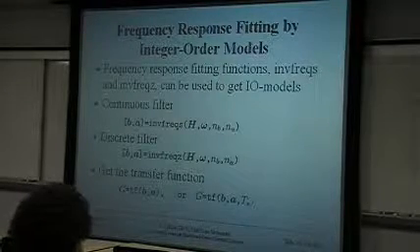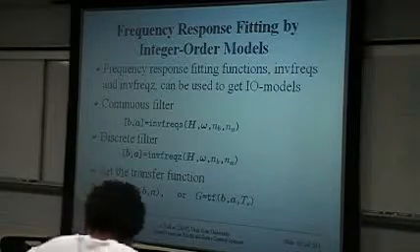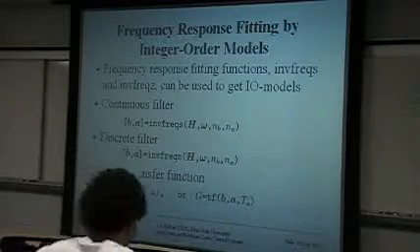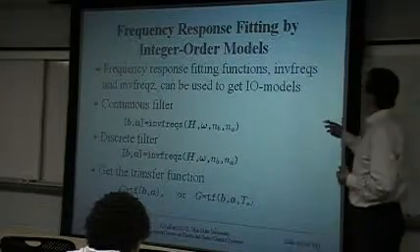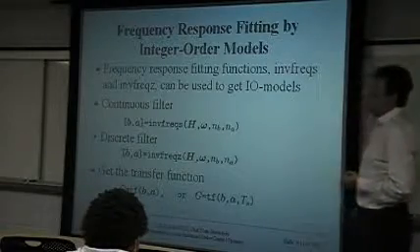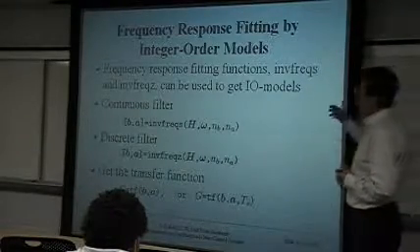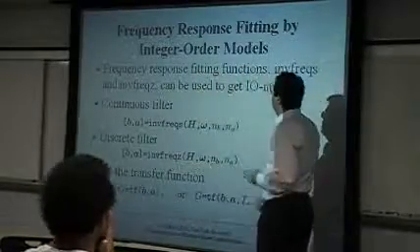And there are other methods to approximate the original fractional order transfer functions as well. For instance, we can get a frequency response first, and then use the Matlab function such as INVFREQS for continuous approximation, or this one for discrete approximation.